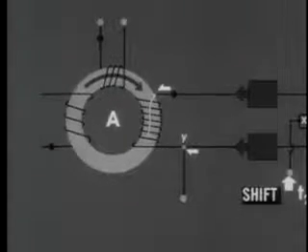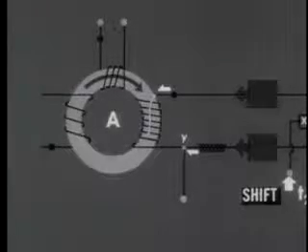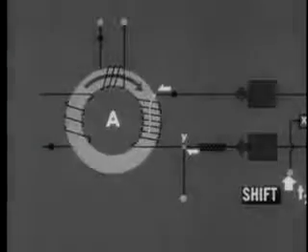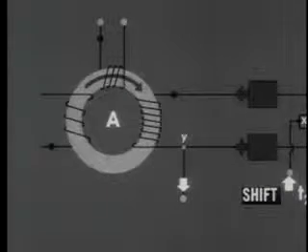As a matter of practice, however, a small coil is inserted into the lower connection to provide a counter EMF there that will balance the counter EMF in the output winding. Therefore, the upper branch pulse meets no more impedance than the lower branch does. The impedances are equal, and so the branches are equal. At point Y, this upper branch current joins the lower branch and flows out of the loop.